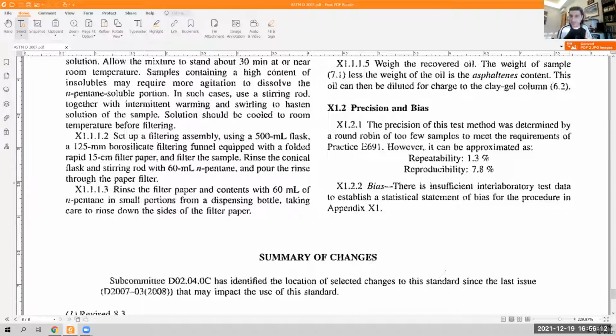Let's remember what repeatability was. Repeatability: you conduct the experiment in the same laboratory, using the same measuring device, using the same personnel, but using different samples. You prepare a sample, you measure it today, you prepare another sample, let's say the next day, you measure it the next day. The difference between them is the repeatability. Well, if you conduct, let's say, 5 of these, then repeatability is related to the range or standard deviation of those experiments. I'm going to talk about that later in more detail.